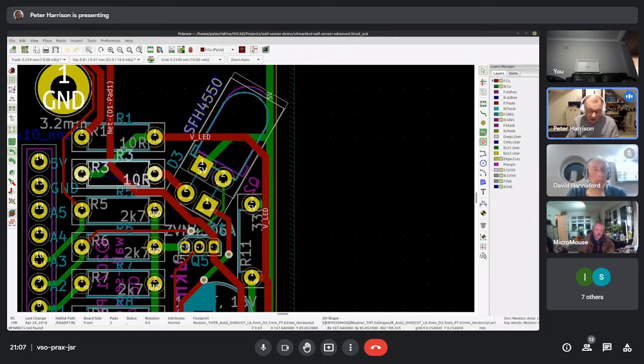Because once you've put the thing on there, it says 10 ohms on it, right? What you need at some point is to know what goes where, but you don't need a thing on there that says this should be a 10 ohm resistor. It's kind of redundant. So KiCad takes the view that this is a fabrication thing, right? You can generate fabrication files that tell you, or you can print them out or whatever to say where stuff goes, but that information doesn't need to go on the board. So let's get rid of that.